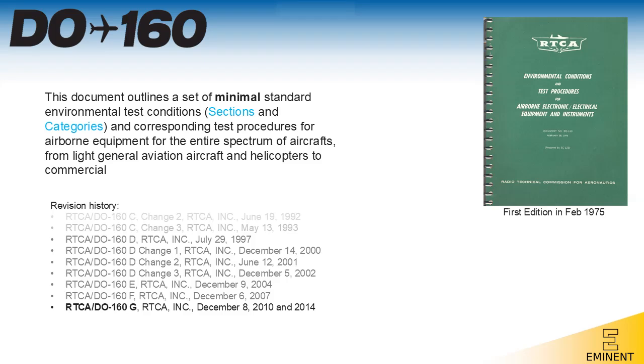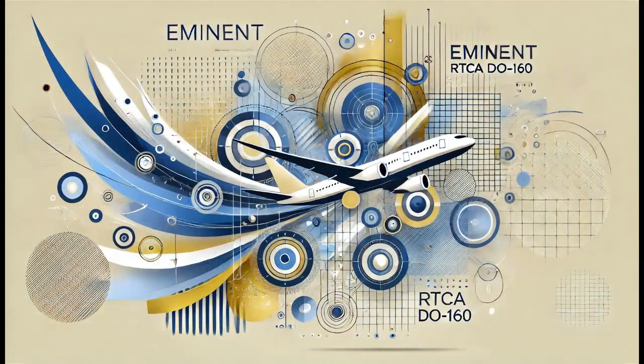Electromagnetic interference, EMI, confirms that equipment is unaffected by electromagnetic fields generated by other systems. Icing and freezing conditions, tests waterproofness and functionality in icing conditions. RF emissions and susceptibility, verifies that equipment neither emits harmful RF energy nor is affected by nearby RF sources. Fire and flammability, assesses fire resistance and limits smoke emission to prevent onboard hazards.